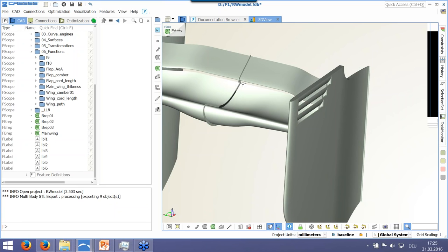When we talk in aerodynamics, it's more important the efficiency, the ratio between downforce and drag. So if you open these slots, you will reduce the downforce, but in fact you will increase your efficiency. So this is the concept behind louvers. I hope I have answered the question.